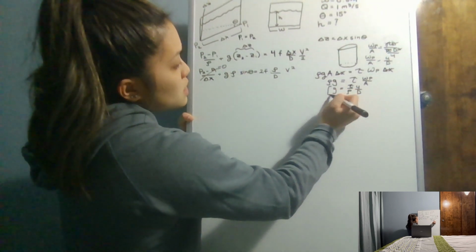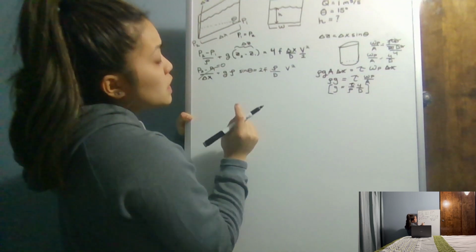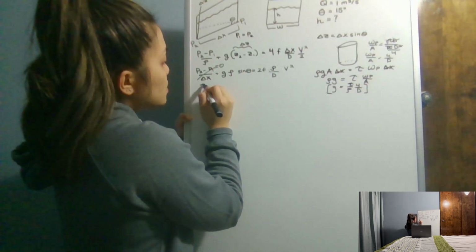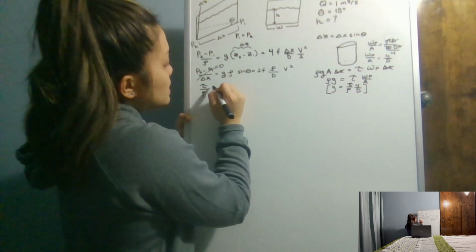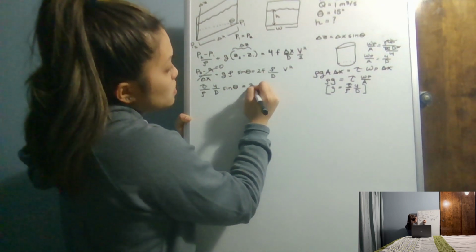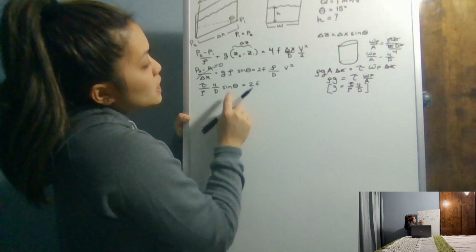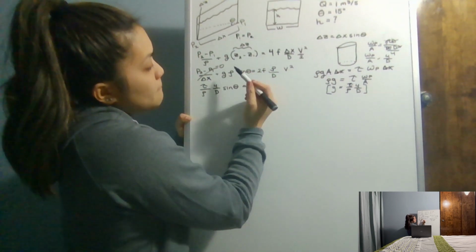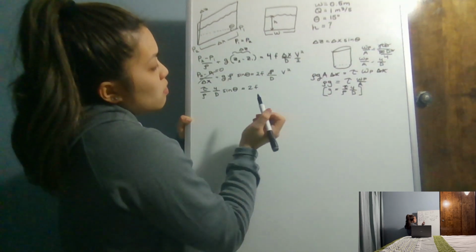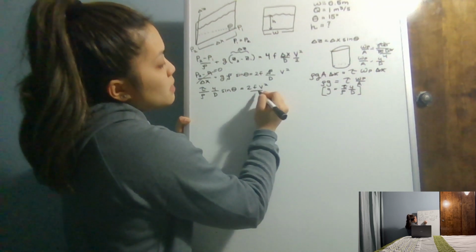We're going to use this equation and plug it in for the gravitational acceleration over here. So we'll have shear stress divided by the density times 4 divided by the diameter times sine theta is equal to 2 times the friction factor. Another thing is that this density and this density actually cancel out, and so sine theta equals 2 times the friction factor times the velocity squared divided by the diameter.